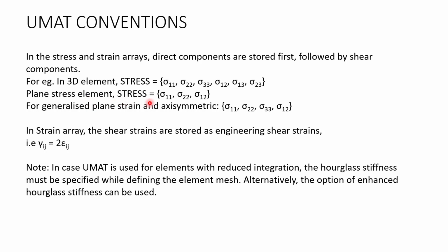If it is for a plane stress element, then we will have only 3 components in total, 2 normal and 1 shear. These are all the in-plane components. For plane strain and axisymmetric, we have 3 normal and 1 shear. The out of plane shears are 0. There is an in-plane shear of sigma 12.